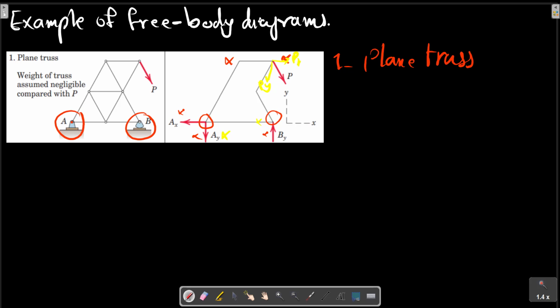When the correct physical sense of a force or its component is not easily recognized by direct observation, it must be assigned arbitrarily, and the correctness of or error in the assignment is determined by the algebraic sign of its calculated value.